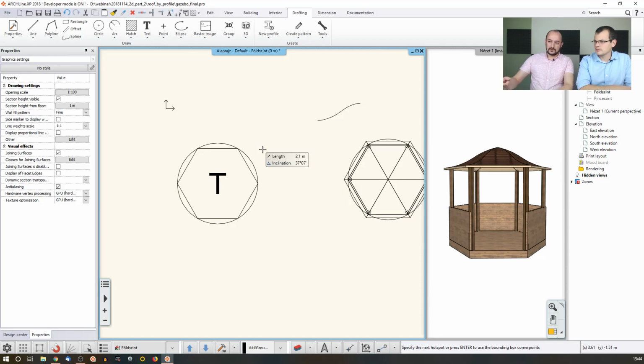Now there is an extra step that I need to define, and what I'm defining now are the reference points. Now there is an important step here. The first reference point will be the first offered. Now when you define more than one reference point, then you can cycle through these later when you place it. Oh, so when you're placing something and you keep on hitting the F5 key to toggle between the reference points, this is where you can actually edit them.